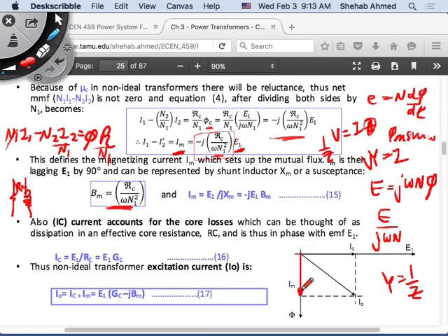We also said that the core has a resistive loss. It's not because of the resistance of anything. It's because we have hysteresis losses and eddy current losses. We said that eddy current losses are actual current flowing in the lamination material, which has some resistance and causes power loss. So it's a real power loss. We represented that as this resistance in parallel with this magnetizing branch. So we have to represent that somehow. We have to find a value for it.